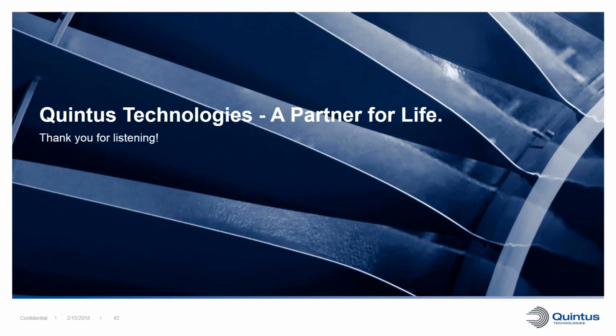Okay, thank you. The next question is from John. What is unique with a Quintus HIP system in terms of safety? Well, as you saw, we are using this wire winding technology, which is fully approved by the ASME boiler and pressure vessel code, as was reported. And these systems are designed to handle the pressures we are talking about. But not only is the pressure important, the gas is as important to think about. Argon gas is a gas that you need to know what you are doing when you are dealing with, which is why we also always have oxygen sensors equipped on our systems.